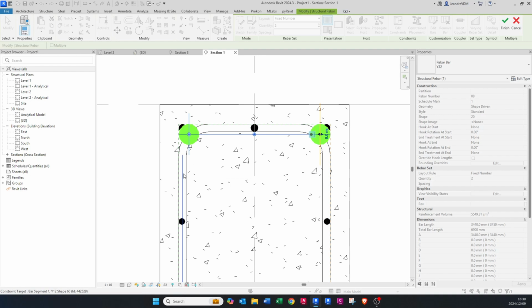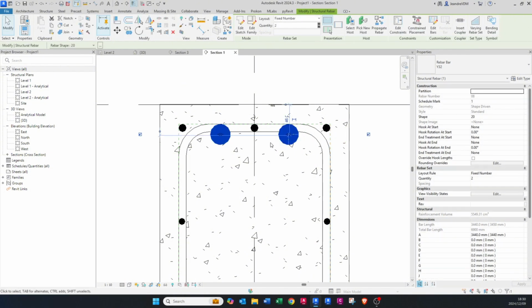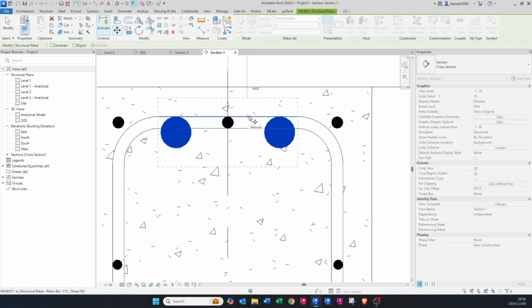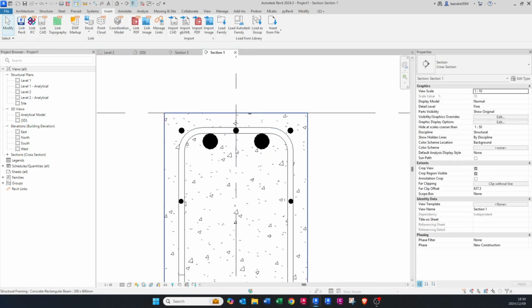I'm going to say I want this bar to go from that edge, let's say by maybe 25 mils, rather minus 25, like that. Let's make it minus 50. That looks better. Then we're going to do the same for that bar, also minus 50. And then you say finish. Then I'm just going to move it, MV on your keyboard, move it down so it sits there.